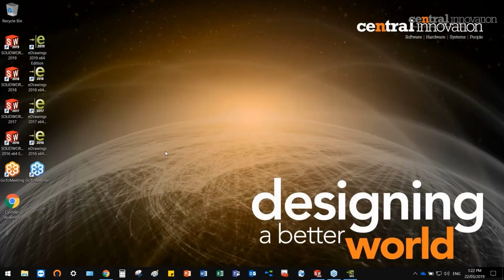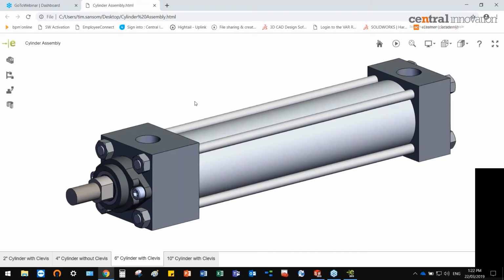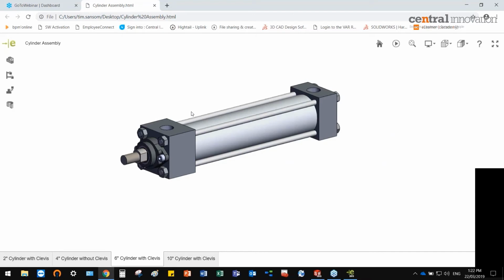You can see I've got a Chrome logo against it because, let's open that up. Fingers crossed, this will open just in a web browser. So if I have eDrawings Pro, I can save it in this format and send this to pretty much anyone in the world. If I'm sending it online, they have a web browser, which means they'll be able to open it. I don't need any kind of viewing software for this particular file type. I can just save it as a web HTML file, and they'll be able to open it up in a browser.